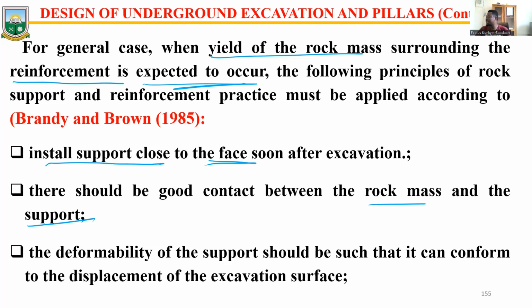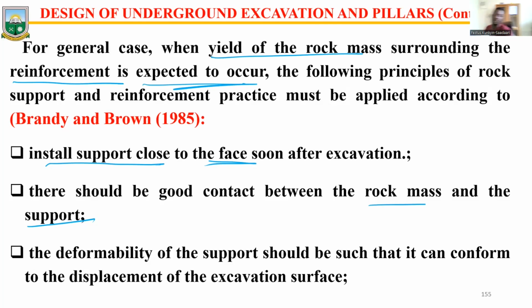Then there should be good contact between the rock mass and the support. And then the deformability of the support should be such that it can conform to the displacement of the excavation surface. For example, what we are trying to demonstrate here is that, let's say this packing case I have here, this is an excavation I have created.